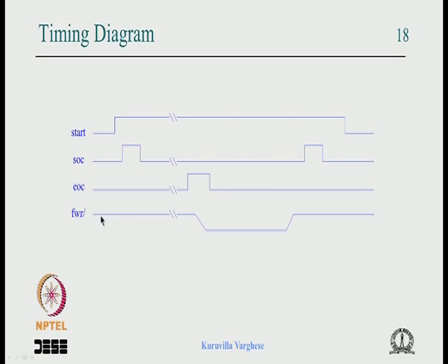Normally the write signals are active low. It is inherited from the TTL kind of logic, where the active high signal does not source much current and the active low signal is the one sourcing the current. Most of the time the write is inactive, so to reduce the current it was made active low. With CMOS that is not a big deal, but anyway this is inherited from the previous technology.